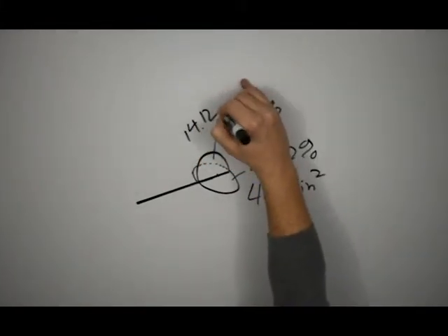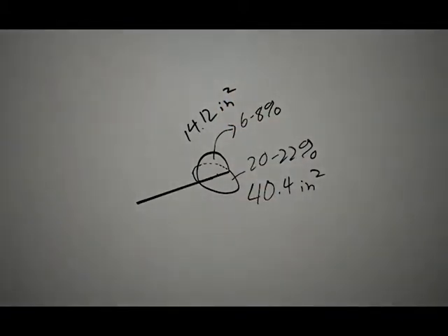Just like with our main wing, we need to select an aspect ratio for our tail. The tail aspect ratio for a subsonic airplane usually falls between 3 and 5. If you stay on the lower end, you're going to have a lighter structure, and if you go towards the higher end, you're going to have less drag. We're going to try and keep our tail light, so we're going to go with an aspect ratio of 3.